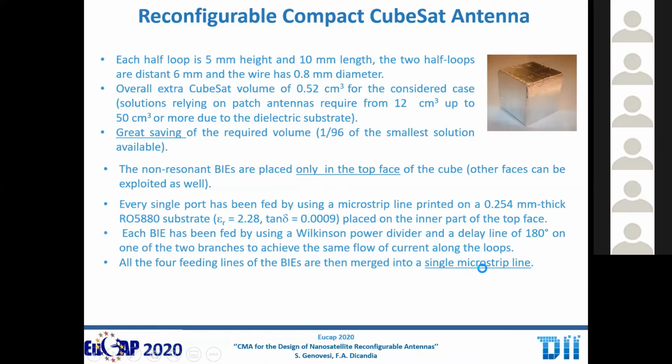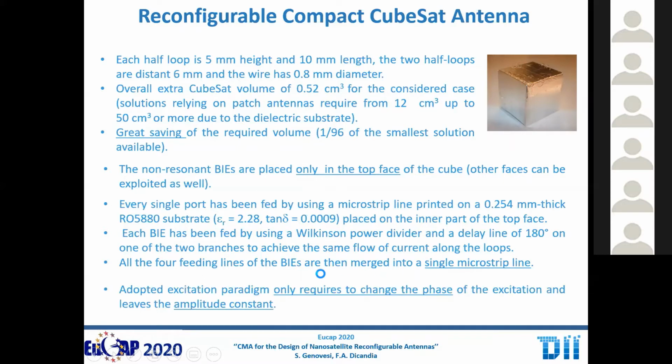a single microstrip line. And another very important thing, we are able, as we show, to steer the beam by only controlling the phase and not the amplitude of each feeding port. So this is also very good in terms of efficiency. And so these are some examples of the final results.